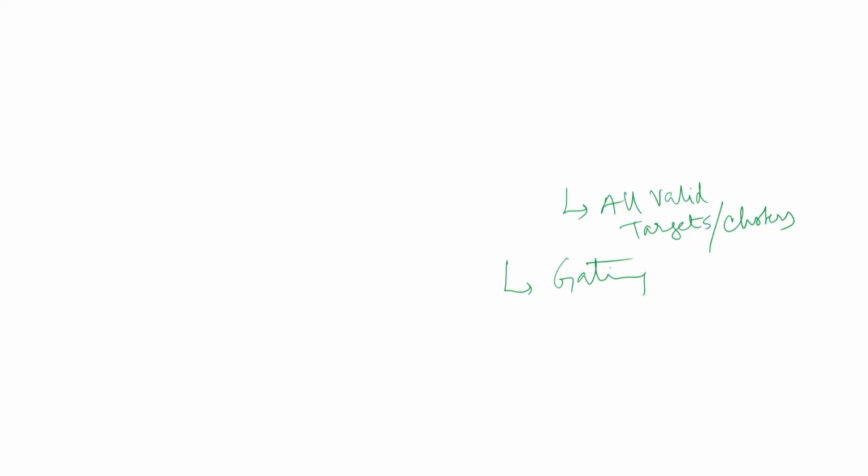First, whenever all the measurements are coming, they are all valid targets or valid clusters. Then we will create a small neighborhood around all the previously formed targets or clusters. The elliptical neighborhood is called a gate, track gate. It could be a position gate, it could be a velocity gate separately, and I will try to qualify all the next scan measurements to the gate. If the measurement falls into the gate, then it is gated, otherwise it is non-gated. Non-gated means I will assume they are false alarms.